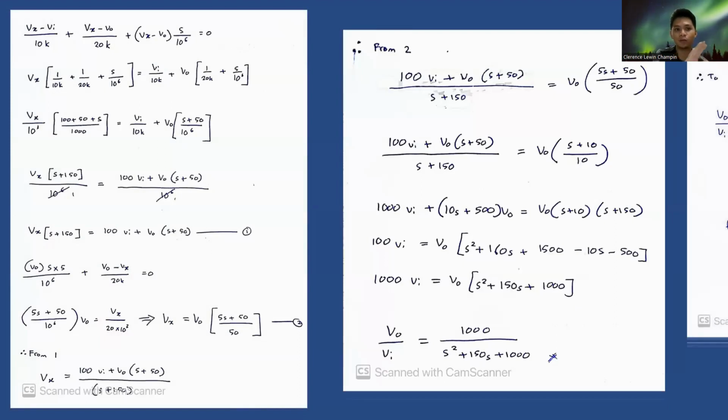So we study the circuit first. You have to analyze and study the circuit before you put down the manual calculation. You need to understand how the path of the circuit works, from the current and also the nodes and the meshes. From there you study and then you bring out the exact formulation of the circuit itself. From there, you will expand and use the Laplace transform theoretically and apply the values to find the output response.